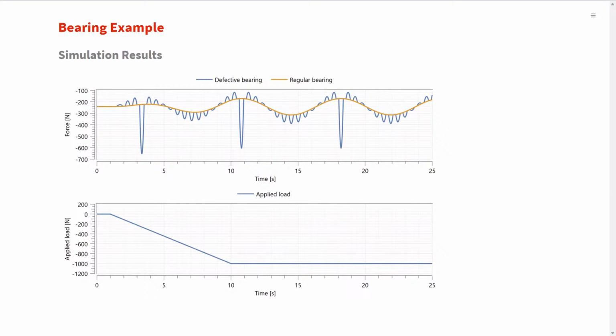Right. In this simulation, we are examining the forces on the roller bearings, where one of the bearings has been introduced with a 0.1 micrometer defect. This defect translates to an approximate impact of 500 newtons. You can check our documentation to calculate the corresponding force from the defect size. For ease and clarity in our model, we represent this defect through a force equivalent method, which simplifies the integration into the system dynamics.